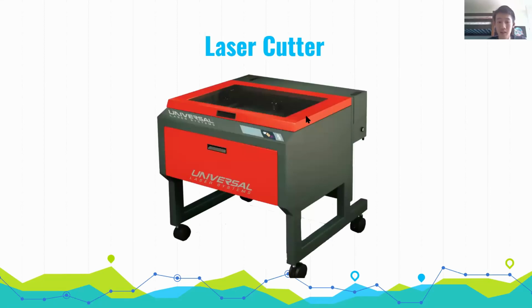Next is a laser cutter. As its name implies, a laser cutter uses a laser to cut out 2D objects from materials like acrylic, MDF, different kinds of wood, and even some specialized metal like some aluminum. The files for this need to be in a vector format, like a DXF or a DWG, because the laser cutter reads those vectors and translates them to the path it takes.